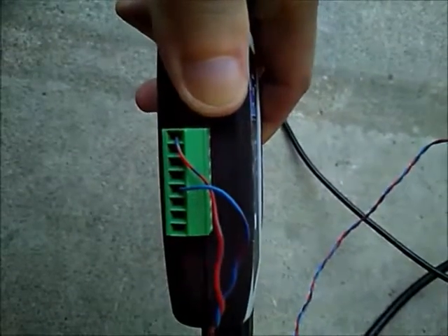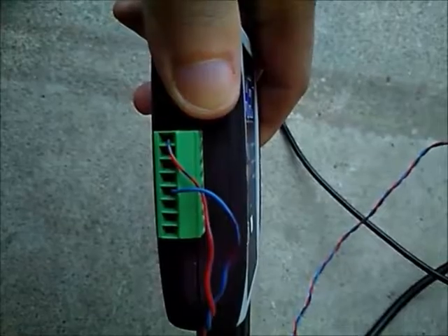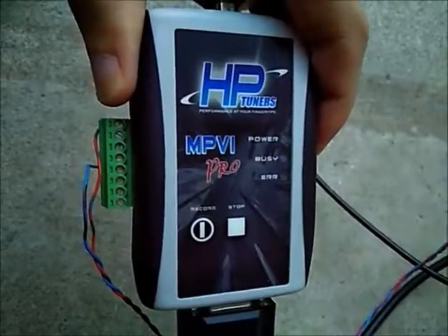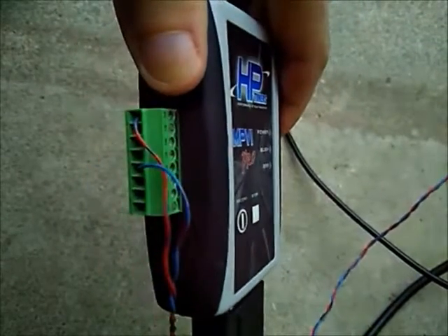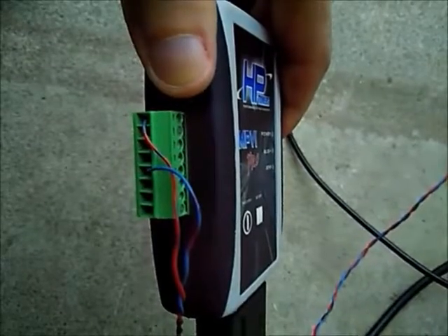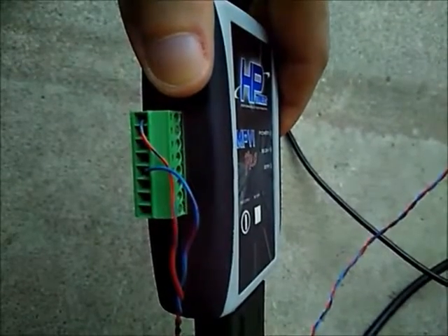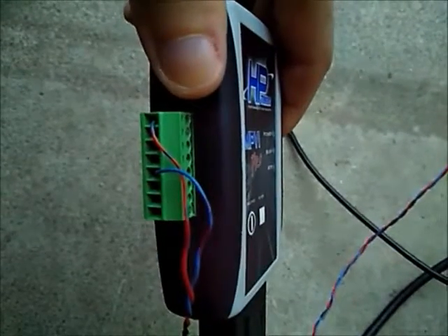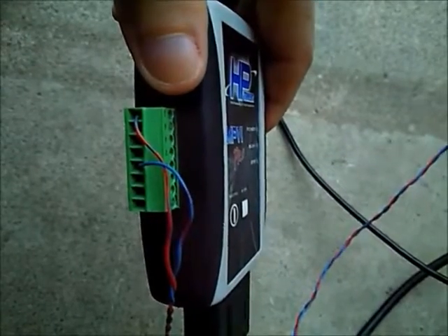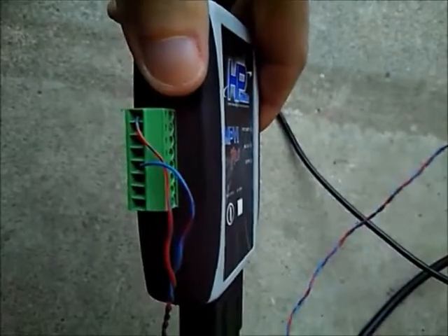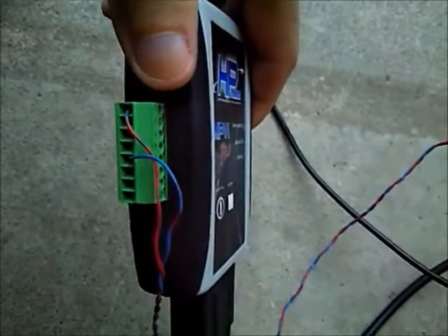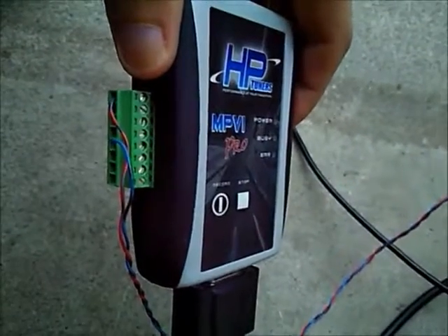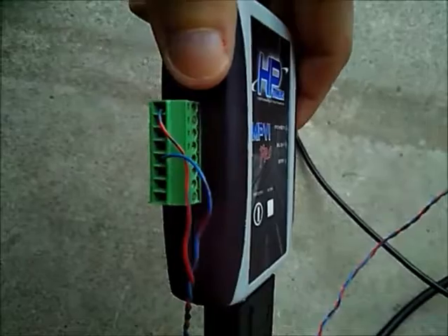So I've got the red wire in the first position, skipped 3 of them, and then the blue one in the 5th position, starting from the top of the unit. And then the red wire being the signal wire, that's going to connect to the signal wire that comes out of your AEM or whatever brand you have Wideband O2 sensor. So that Wideband O2 should have a diagnostic wire and a ground wire. You hook up the diagnostic signal wire to the red one and the ground wire to the blue one, and put them in the positions that you see here. And then when you go into HPTuners on the computer, you should be able to find it under channel 1.